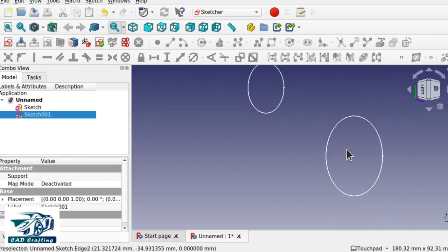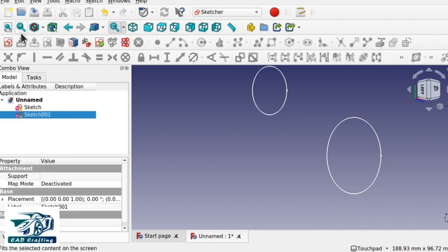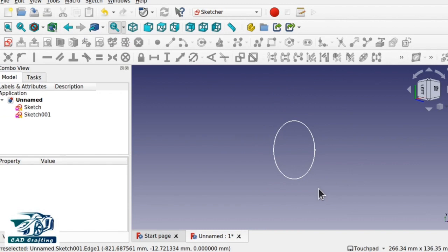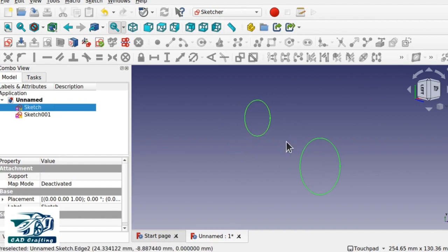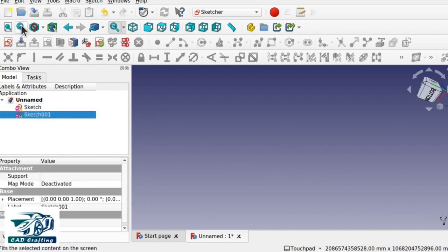Let's zoom in here, and this time let's select that new sketch we created and go fit selection, and that brings that sketch into the center of the screen. Click the other one, fit selection, and we've gone to the other side as well. So I'm flicking back and forth between the sides, and that's important because you'll get yourself lost. Say if I really zoom out and I just add in some rotation, I don't know where everything is, so I want to go back to this sketch and go fit selection, and we're back in business.